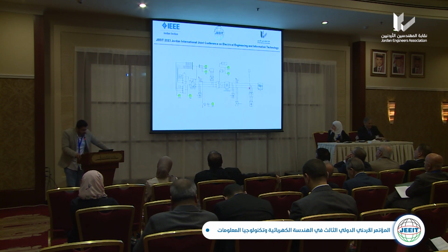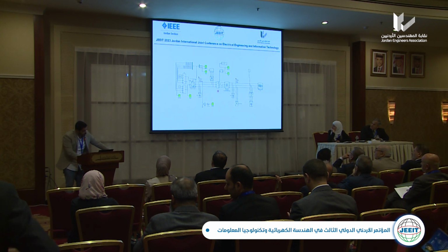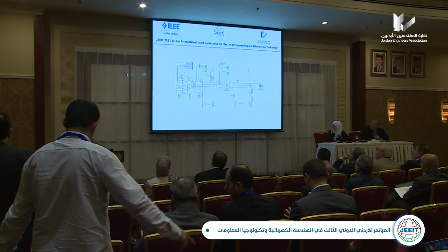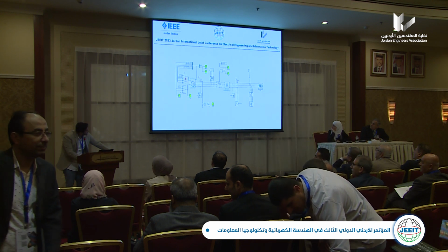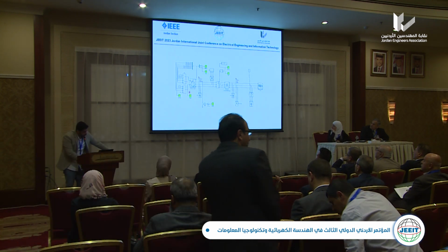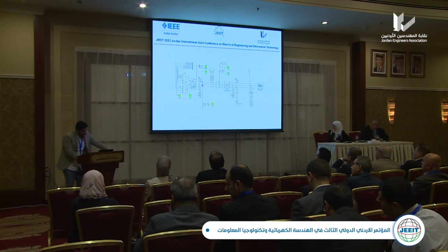Okay, now this is the single machine infinite bus system. It is an emulation, or a testing, for the first stage of the IEEE 9-bus system, but the IEEE 9-bus system testing was in the complete thesis. This is the first stage in testing the synchronverter, which is a single machine infinite bus system. We have a three-phase real synchronous generator, a hydraulic turbine, and an exciter control, the field voltage control.